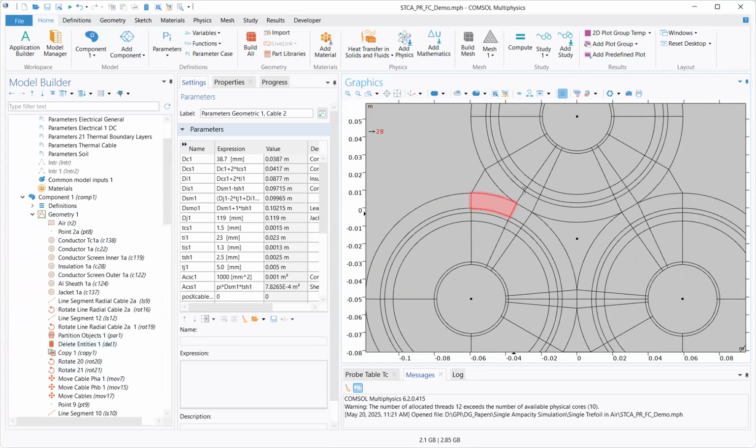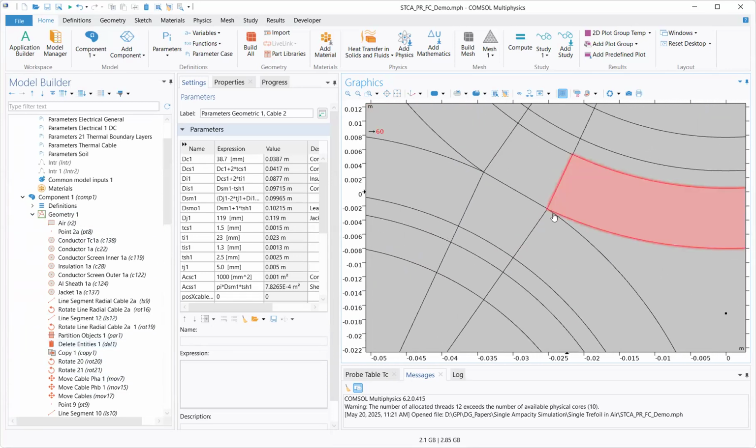Because like we mentioned in the last class, in the region here where the cables come in contact, if we don't put effort to create and control the geometry here, then the mesh will degenerate into mesh elements with very low quality, and that could cause divergence of the solution or inaccurate results. But most likely, not inaccurate results. Most likely, it's just going to be a convergence problem. So you want to minimize that.